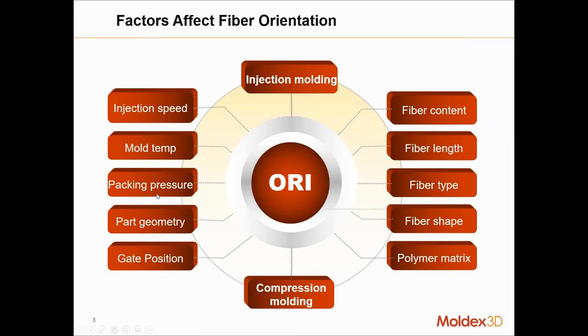And there's two ways that we can really run a fiber orientation analysis. You can either do it through a traditional injection molding process, where the pellets will actually have those fibers contained in them. There's also a specialized process where the fibers are introduced into the polymer and into the mixture right as the pellets are going from the hopper into the barrel. So that's actually kind of cool. There's a lot of adaptations that have been made in injection molding to facilitate a more controlled fiber orientation scenario.